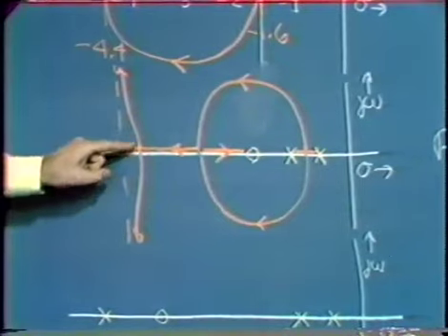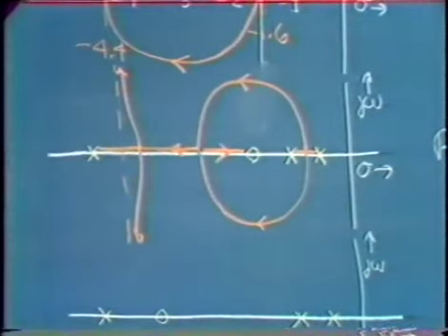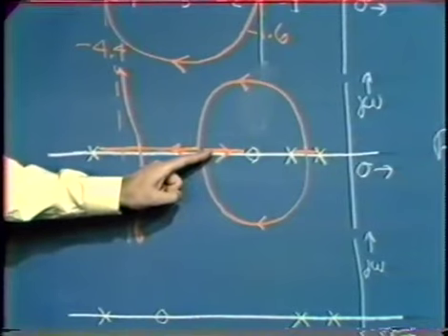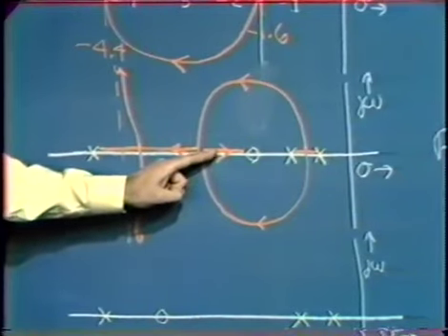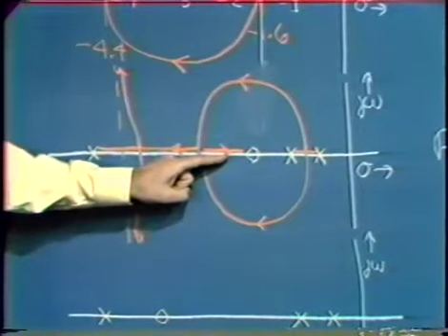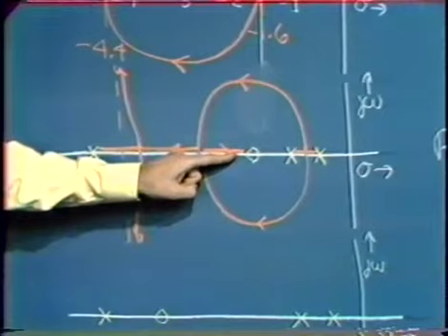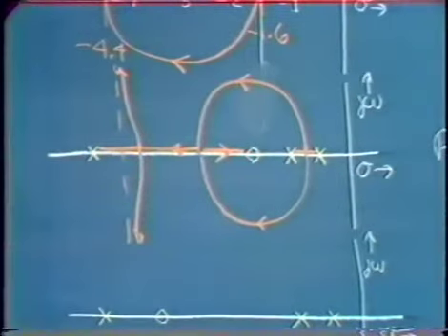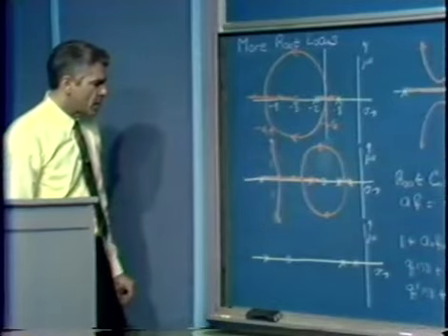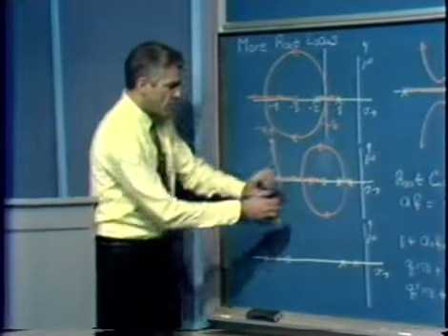The reason for this pair of branches moving away, or we can argue that reason, by considering the average distance rule. Here we notice that as we increase A naught, F naught, this branch is still moving to the right. Consequently, in order to keep the average distance of the branches from the imaginary axis fixed, these two branches have to move somewhat to the left. Once again, if we had exact numbers for all of these things, we could do a more precise calculation. But at least we see the general behavior.